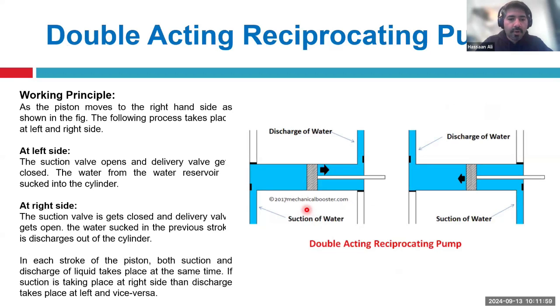During the first stroke, I will not call it a suction stroke because essentially it's not only a suction stroke. In the first stroke, your piston is moving backwards. Your suction port of one side will open. The discharge port is remaining closed. But this fluid motion will actually open the discharge port on the second chamber.